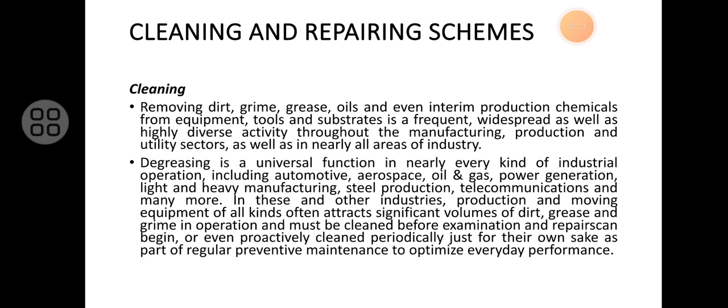A surface preparation method is adhesive bonding or adhesive joint strength. The degreasing operation was performed by three methods: rubbing, spraying and immersion. Strength tests were performed on single lap adhesive joints of hot-dip galvanized material sheets made with a localized adhesive according to the above variation of surface preparation.